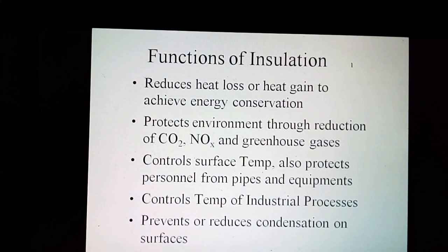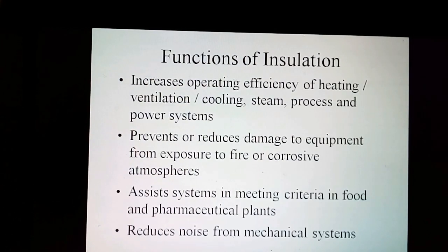Function of insulation. Insulation is used to perform one or more of the following functions: reduce heat loss or heat gain to achieve energy conservation, protect the environment through reduction of CO2, NOx and greenhouse gases, control surface temperatures for personnel and equipment protection, control the temperature of industrial processes, prevent or reduce condensation on surfaces, increase operating efficiency of heating/ventilation/cooling, plumbing, steam, process and power systems, prevent or reduce damage to equipment from exposure to fire or corrosive atmospheres.